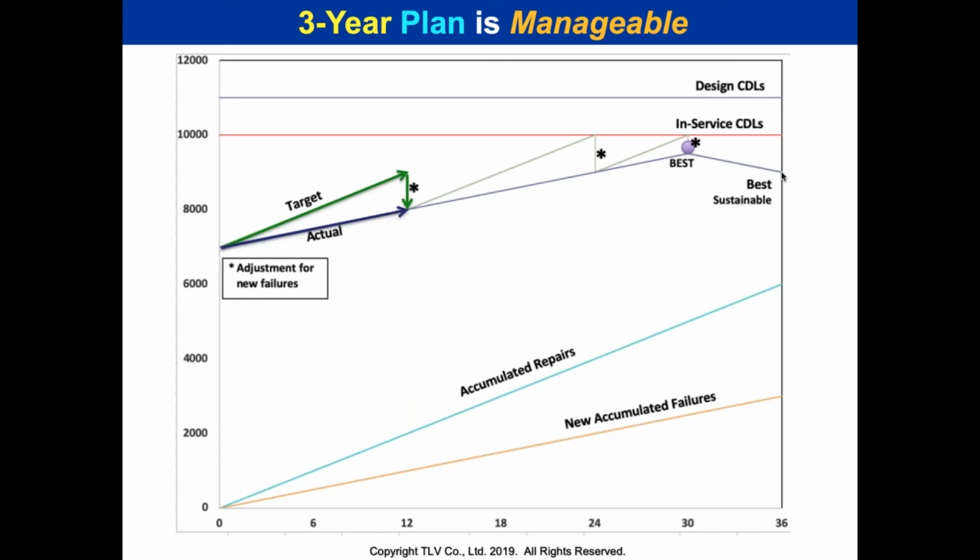I'm telling you, please read that article, Why Bad Things Happen to Good Steam Equipment. For every year that you have a gap year, that you are not proactively attacking your steam trap population to keep them in good functioning order, it's going to take you about 3 years to get back in shape. And you can't operate at optimal production if you have suboptimal steam quality. Please think about that.